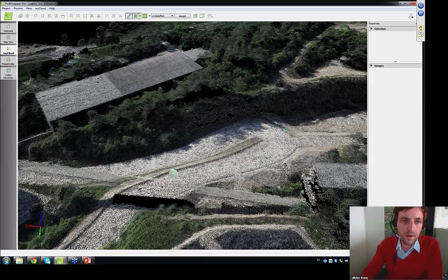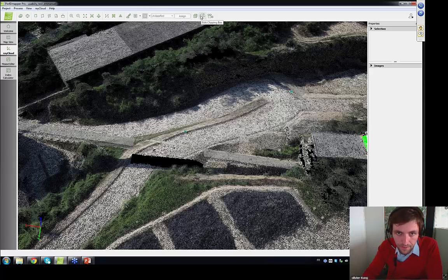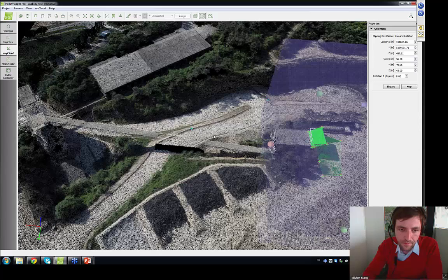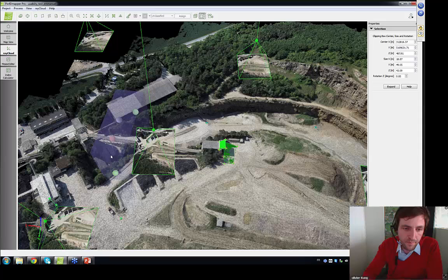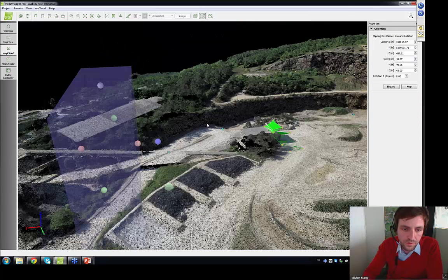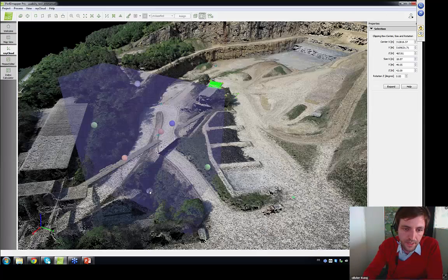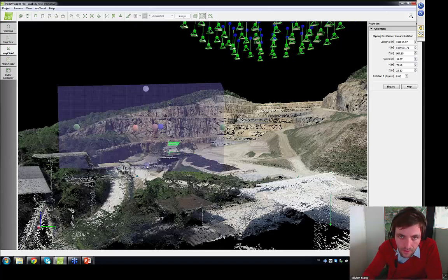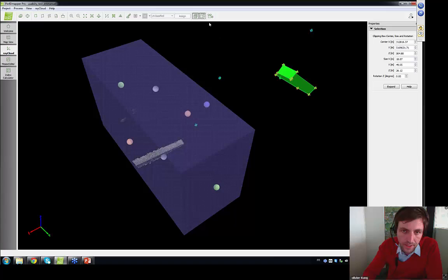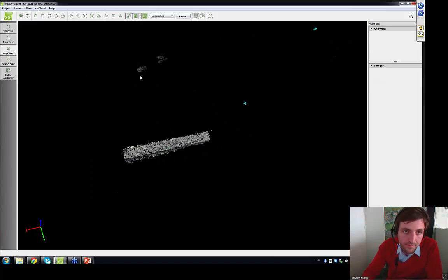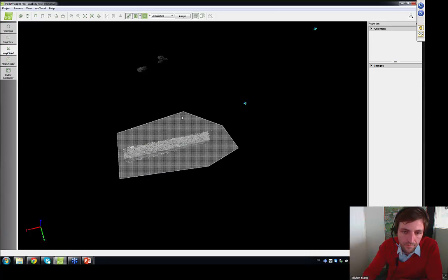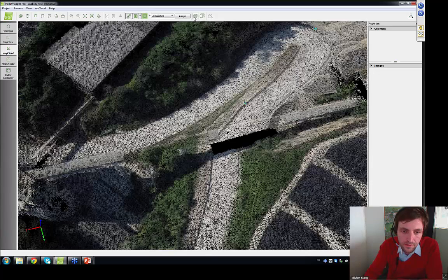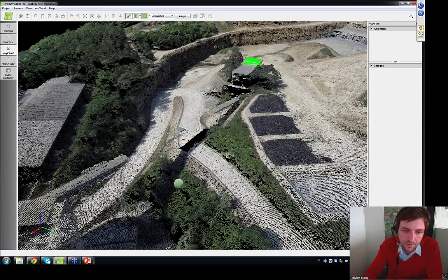So what can you do? Well, I would advise to use the bounding box tool that we have there. So this is the bounding box tool. You would shift it there, and on the altitude you will make sure that only the conveyor belt is within the bounding box and not the volume below. So a bit more like that. And when you clip, now you only see the conveyor belt. So that means that when you delete these points and you remove the clipping box, you just deleted the points which are on top of the conveyor belt, and you didn't remove any points which are below.